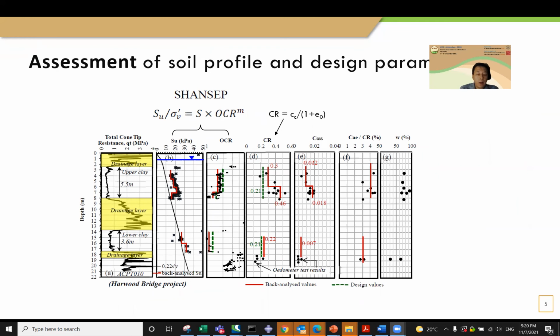When we are looking at the back analysis in step 2, it is important firstly to review the soil stratigraphy based on the nearest CPT to the monitoring point, as opposed to using the original soil model for design, because the design model was usually developed for a bigger area with the deepest soil deposits. So using the design model for back analysis may give unconservative results.